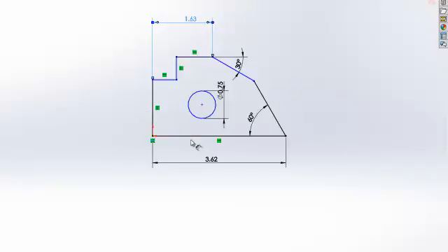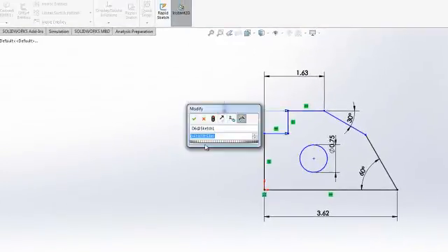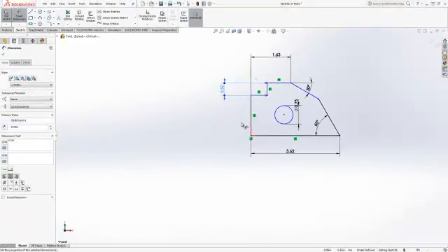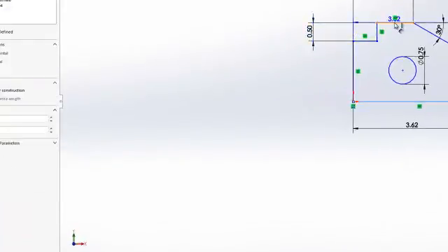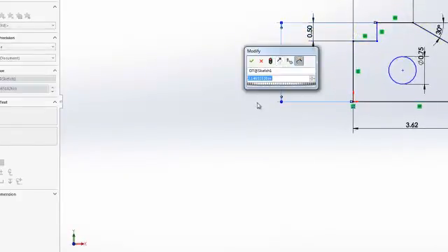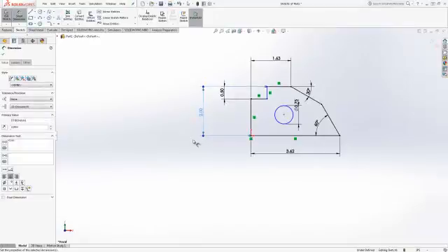The whole thing is 2 inches tall, but, and here's a little but, you need to think about how far it is from some smaller points and make sure that it doesn't accidentally move another line past another line, because depending on your measurements that you start with, sometimes you can actually goof up and cause lines to move and the shape distorts. And so sometimes it's trial and error on figuring out what you need to dimension first to make it do what you want to do. And that just comes with experience.